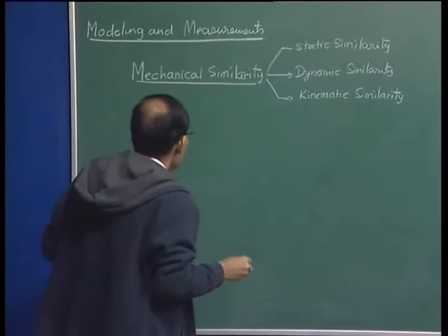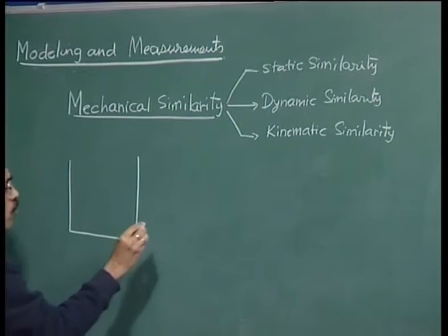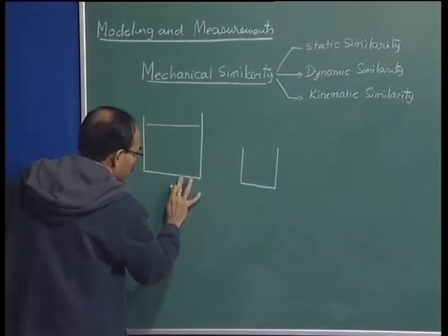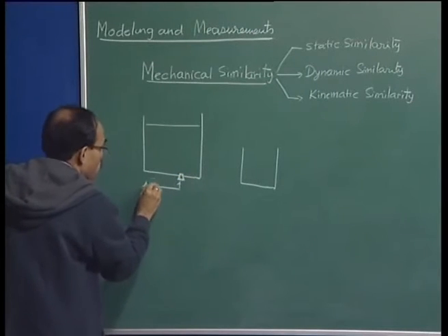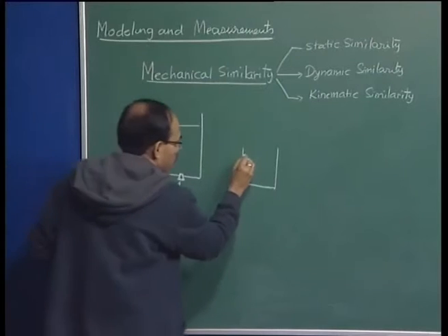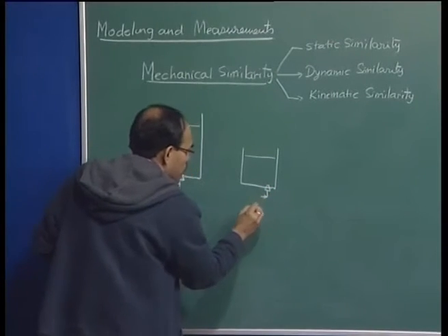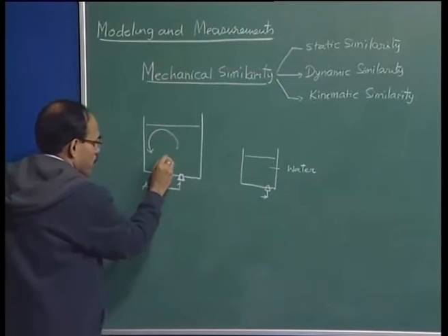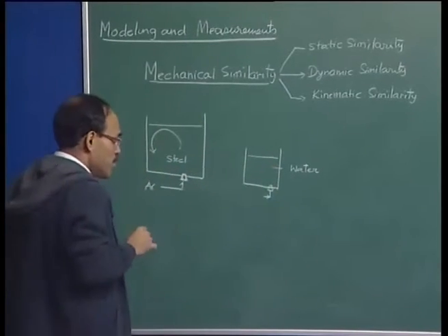Now, two systems. So let us again draw that. We have a ladle model. For the time being, let us see that we have molten steel here and how the molten steel is being agitated. So suppose we are putting in some argon here and there is movement. Similarly, we have here, we are putting in some gas. We have not molten steel, let us say water, and there we have steel. So, let us accept for the time being we can use water. I am going to of course explain that to you in a minute.